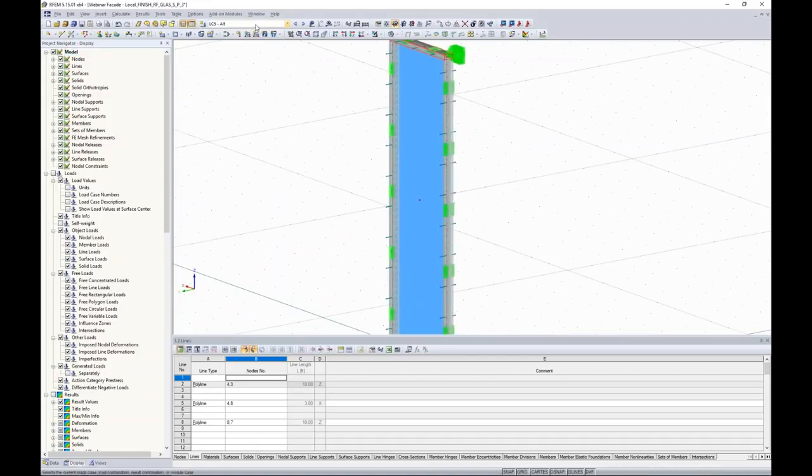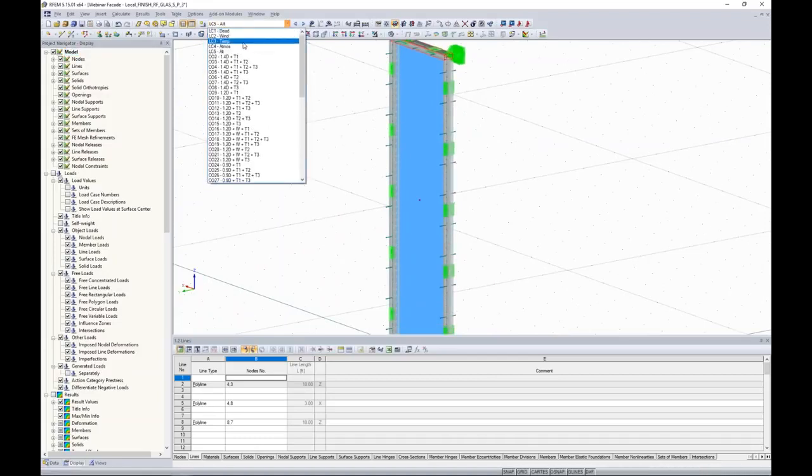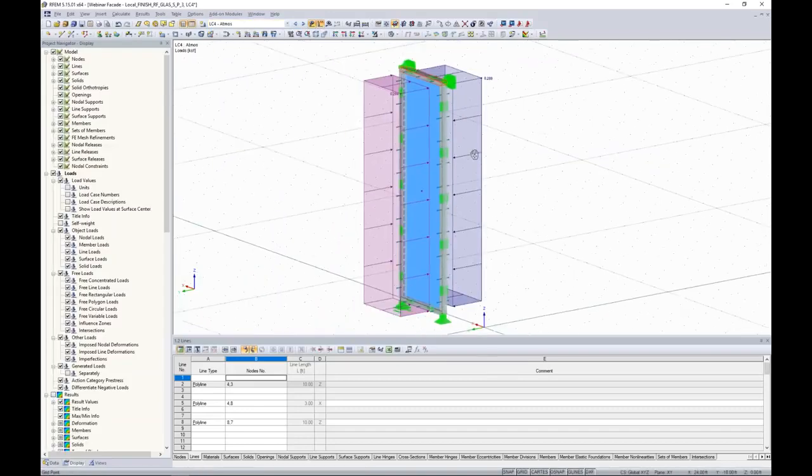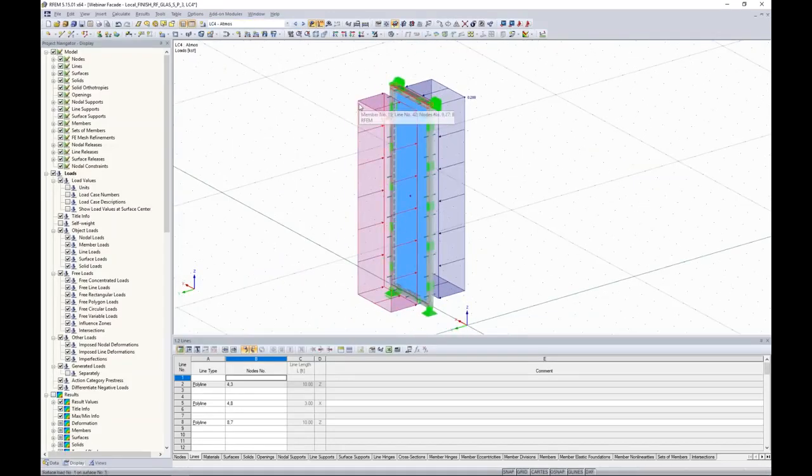And even further, you can take a look at the applied loads. We have the temperature loads, the atmospheric pressure shown here. Again, I've applied 50% to the external, 50% to the internal. You can vary this how you see fit, but this is what the program's coming up with for those gas pressures applied to the surface, applied to the solid elements based on those calculations. Same thing with altitude as well. So it's kind of interesting seeing what's going on behind the scenes with a local calculation.